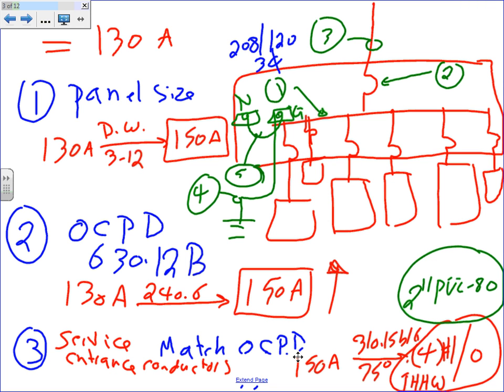Schedule 40, schedule 80. I'm coming from a transformer to the side of the building here, going up against the wall into an elbow and getting into the building. Somebody could drive his car right into that conduit. Physical damage, schedule 80. I like to default to schedule 80 for 2 reasons. Number 1, I'm the engineer and I don't pay for it. That's not a good argument, right? Number 2 is if you're schedule 80, you don't go wrong under any circumstances. But value engineering, you walk in and say, well, schedule 80 is going to be expensive, we know there's no physical damage, I want to go schedule 40. No problem.